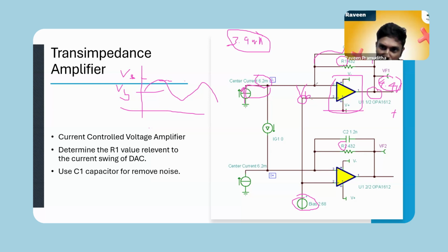You know about the op amp circuit, there is no difference between the voltages. So we can get the voltage difference as 4.4 minus VB. When we are considering this diagram, the maximum voltage we can reach is 4.4, and this voltage swings around the VB. After subtracting VB from 4.4, we can get the voltage swing. So the voltage swing equals the current through this resistor times R1.